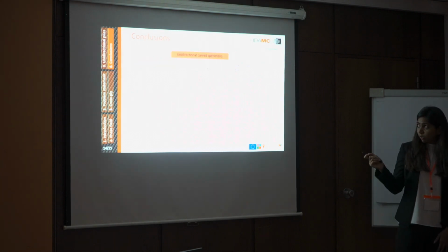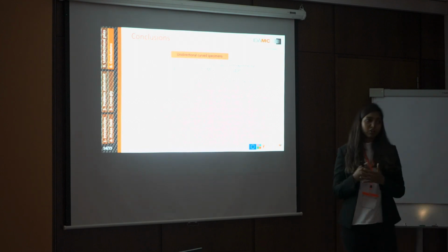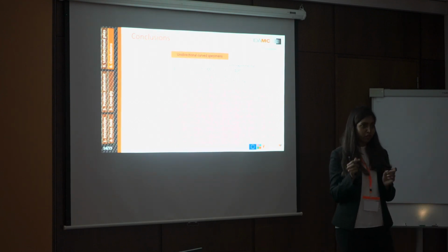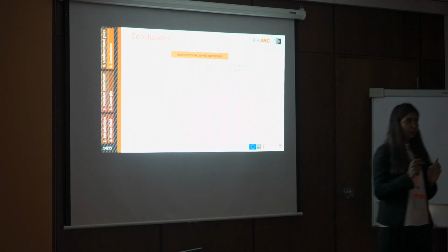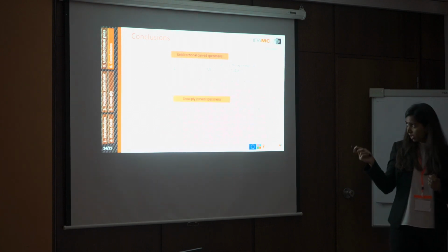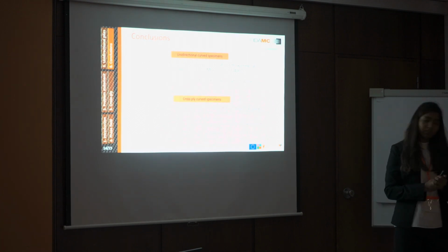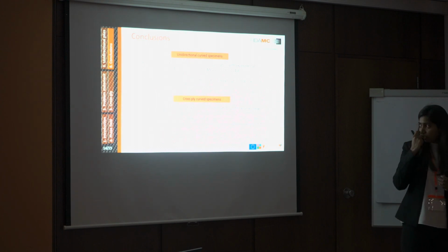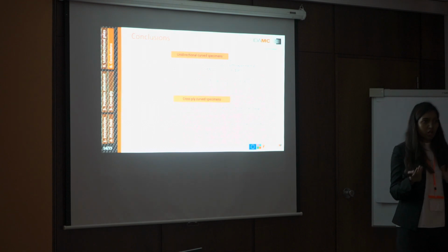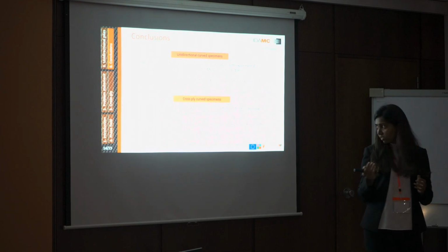So coming to conclude my talk, for the unidirectional throat specimens, we had very good correlation with numerical and experimental failure moment values, validating the usage of cohesive elements for damage modeling, that is interlaminar delaminations. And for the cross-ply specimens, as I already mentioned, the transverse crack is not perpendicular but at an angle because of the domination of interlaminar shear stresses.